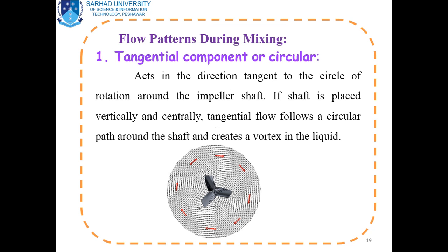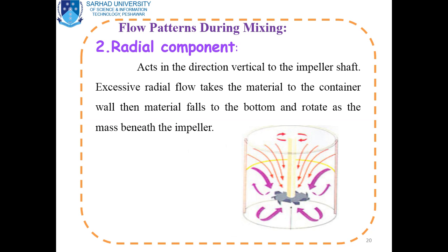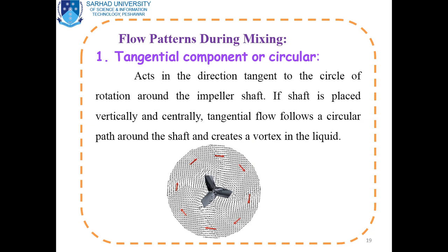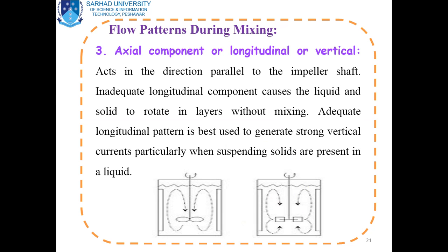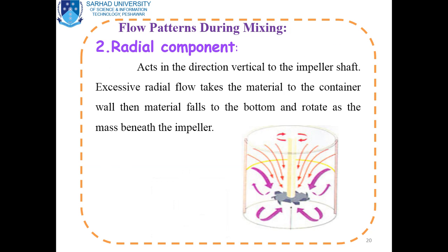There is certain terminology we have used in the discussion related to the flow patterns during mixing. There are three flow patterns. The first one is the tangential component or circular, the second one is the radial component, and the third one is the axial component or longitudinal or vertical component. These are the flow patterns we observe during mixing of liquid.